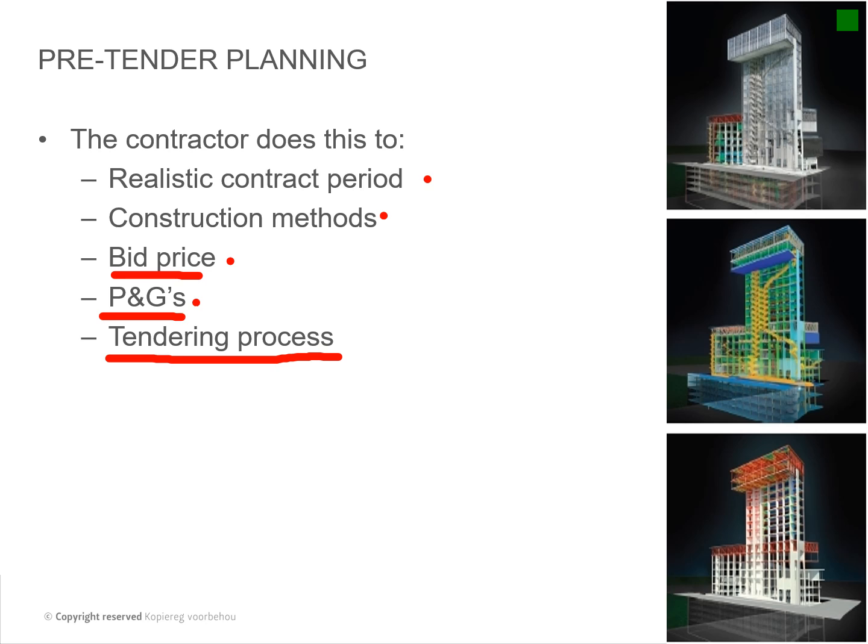If it's longer, you include a bit more, or you price only up to that month and qualify that within your tender document. And then the tender process: obviously you need to know how long the tender will take, and how long until you might be appointed. The rates may have gone up or not, so you have a bit of inflation built into that as well.